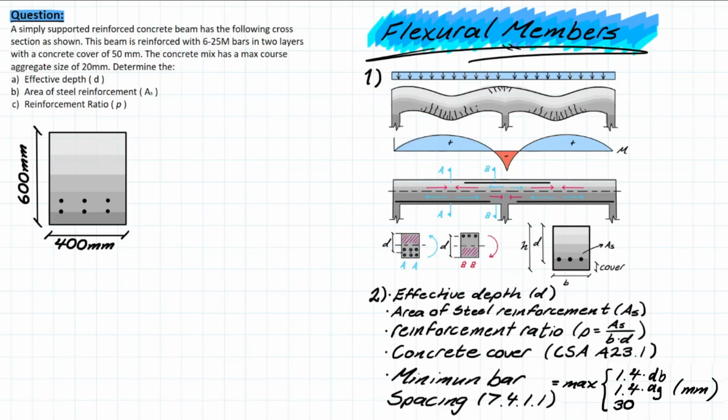And pretty much all that means is that you're transitioning from an area that has positive bending moment at the midspan and a negative bending moment at the supports. And that's typical for not just concrete members, but continuous members in general, where at the support you're going to be developing that negative moment.